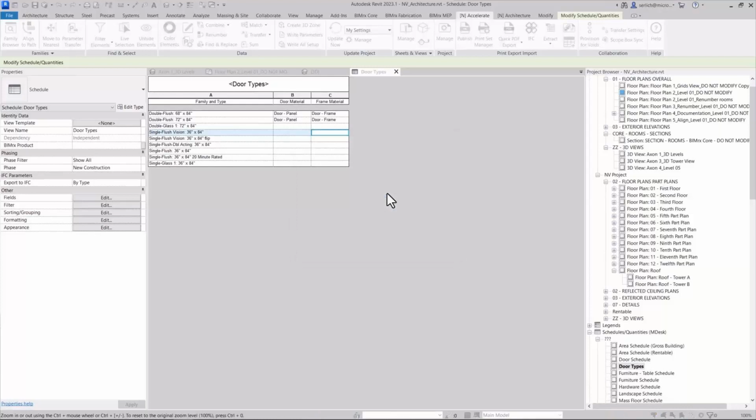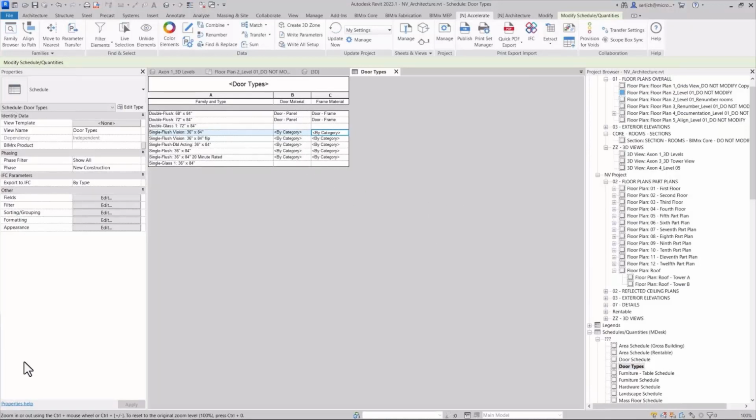But once we hit that go button, it'll ask us to override those families because it is opening the family, running or adding the parameters and loading it back in. But once we've done that, we can see that that field is now editable in the schedule because those parameters now exist in the family. So two features to help with managing, well, first for modeling families and then managing the parameters in families that have been added to the families group in the Accelerate tab.